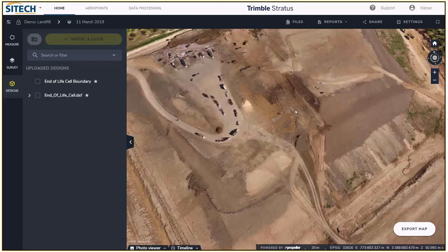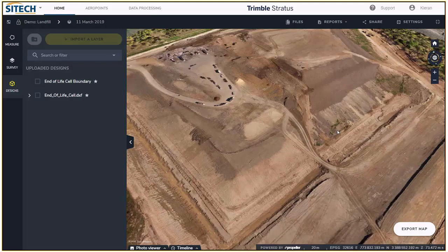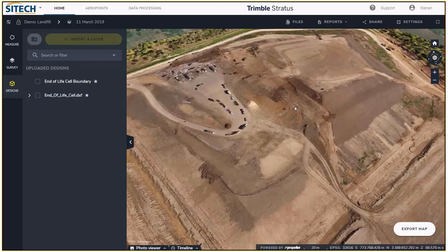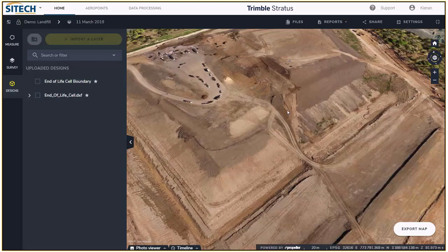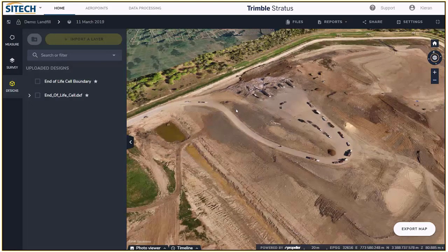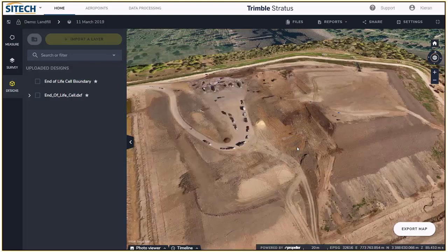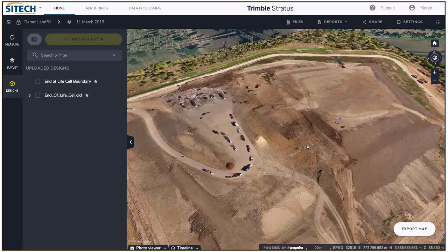So you may integrate some terrestrial laser scanning, some mobile laser scanning as well, potentially merge that with the UAV data set and then re-import that point cloud so that you're not missing that piece of infrastructure or that feature that you needed that TLS data from. So we've seen that once or twice as well.